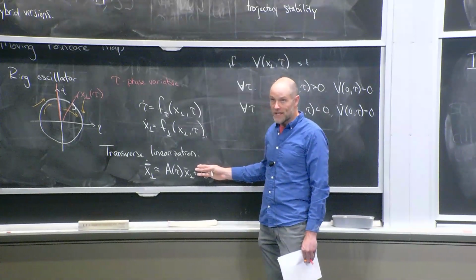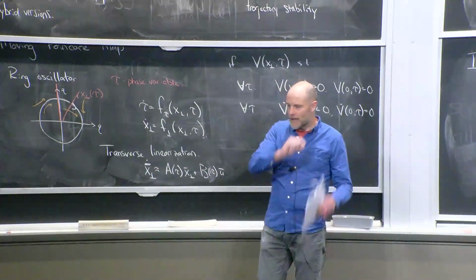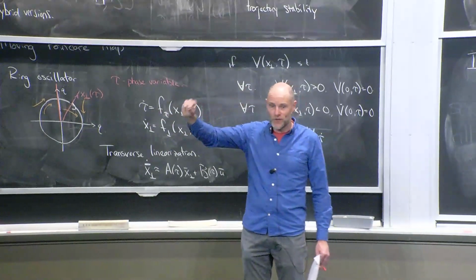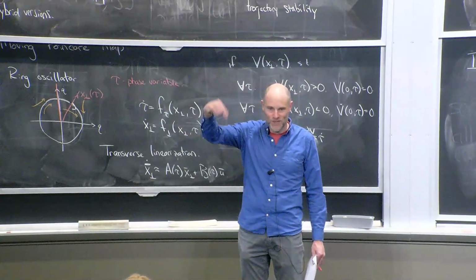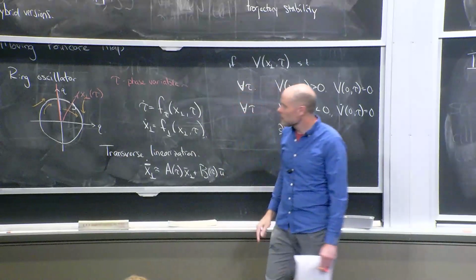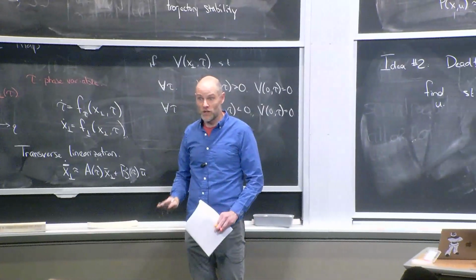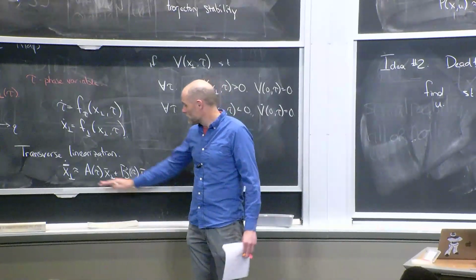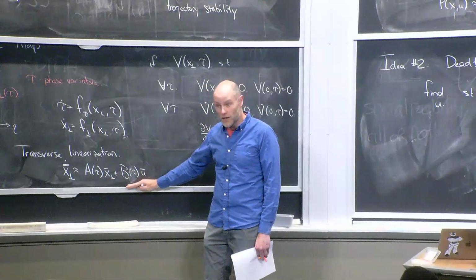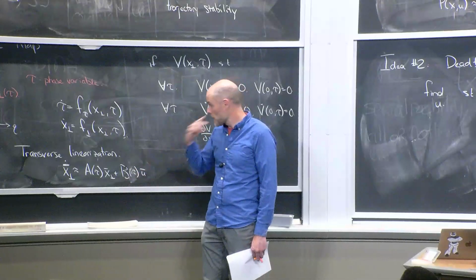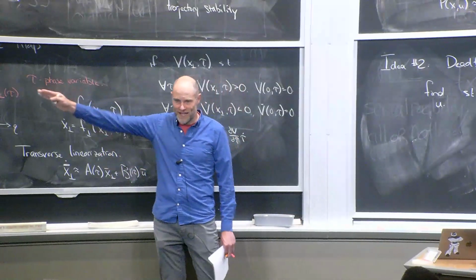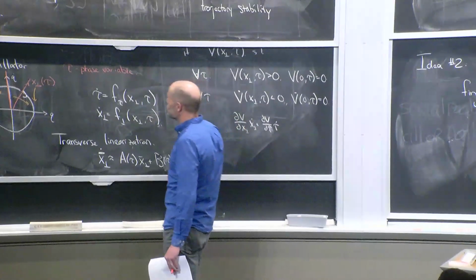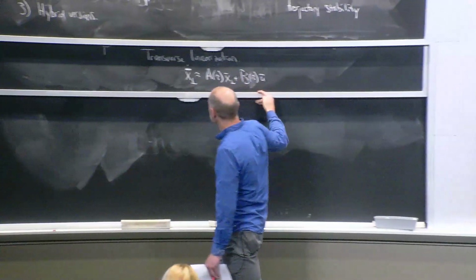Remember back when I said it's tempting in LQR to just say, let's look along the trajectory at the closest point and just project and use that K. You can't do that for time-varying LQR. You can find situations where that would blow up on you. But if you do the LQR in the transverse coordinates, then it is exactly doing that. So if you wanted to do transverse LQR now,